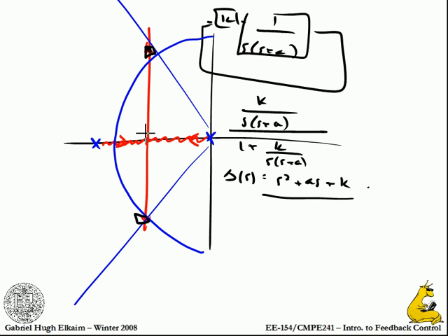So these are now the kinds of oscillations you're going to notice. With something that's particularly well damped, you actually won't notice anything within about a 30-degree cone of the real axis, because it effectively doesn't go through any cycles. We're talking about less than a 5% overshoot. It won't rebound. You won't come back. So when you start to oscillate, you're getting up past the 45-degree line, and you'll start noticing it start to shake.